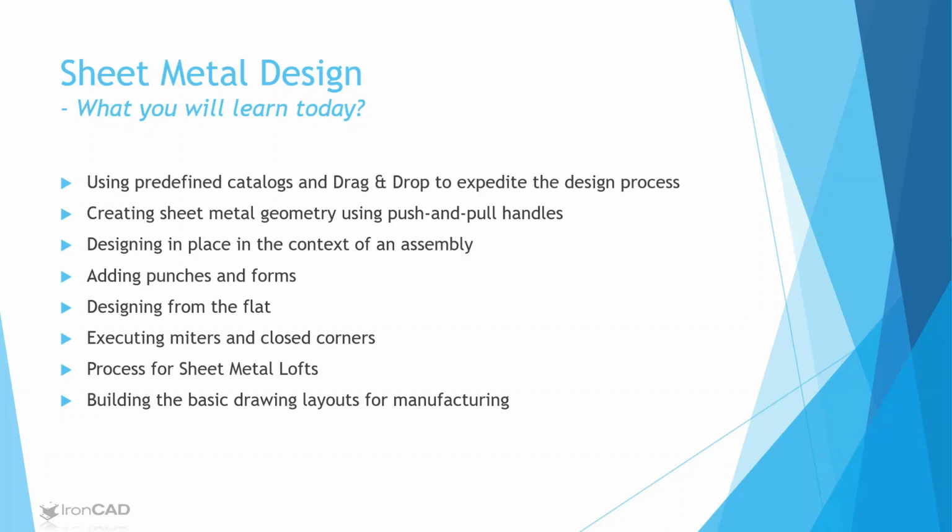And we'll also show you a little bit about sheet metal lofts in IronCAD and how you can create loft geometry and unfold that for press brake manufacturing, if you wish, to have those type of bend lines, for example, in your lofts. And RJ will give you a good example of that in the demonstration.